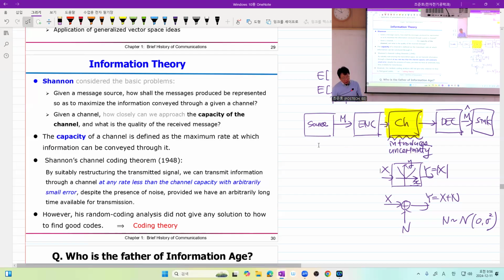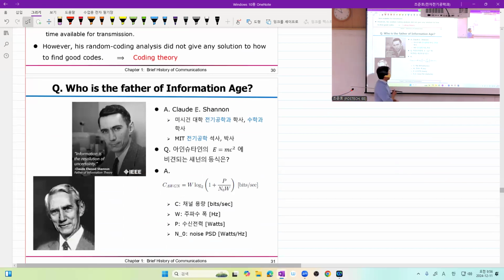And interestingly, Shannon developed a mathematical theory and says that as far as the additive Gaussian noise channel with band-limited Gaussian noise is concerned, your additive Gaussian noise channel actually can still be used as an error-free communication channel. And without error, you may still achieve a positive transmission rate, bits per second, as long as you have some non-zero power and some non-zero bandwidth. This is an amazing result and shocked everybody. It really contradicts our intuition. There is noise. How can we completely remove any possibility of making an error or making a statistical inference on the transmitted symbol?